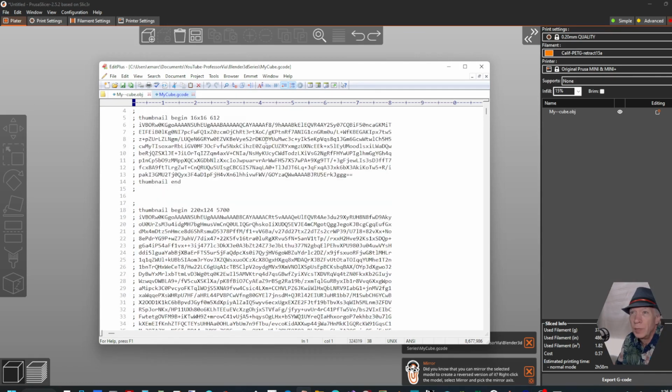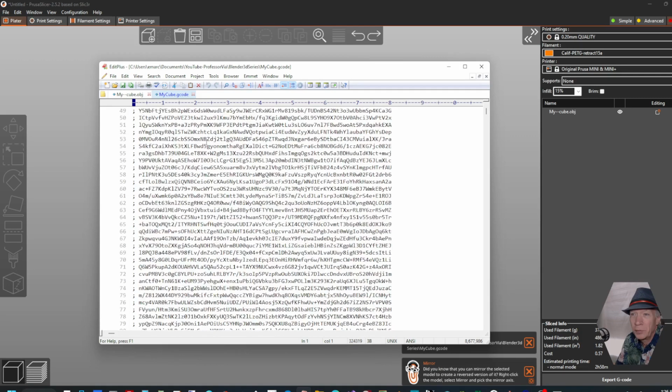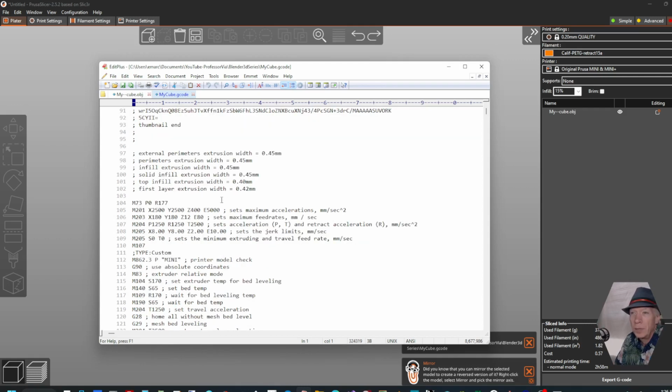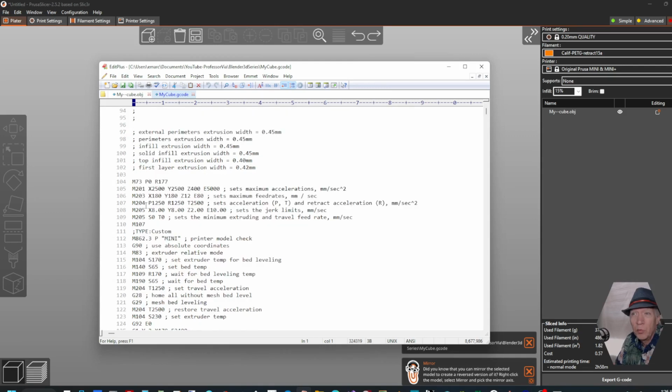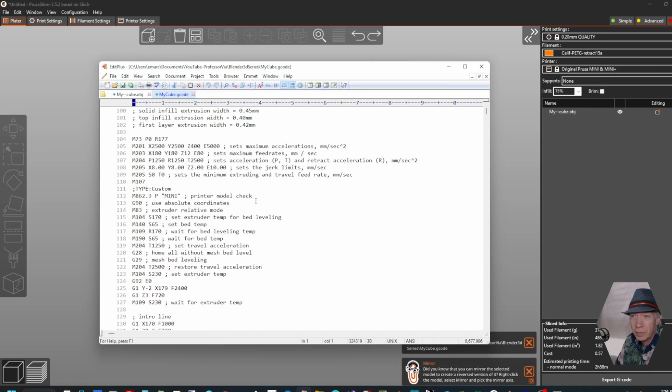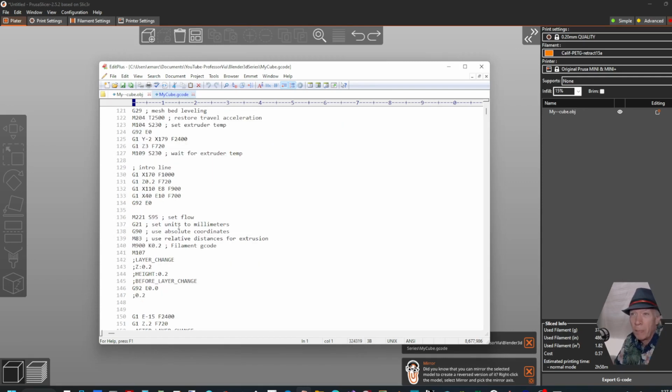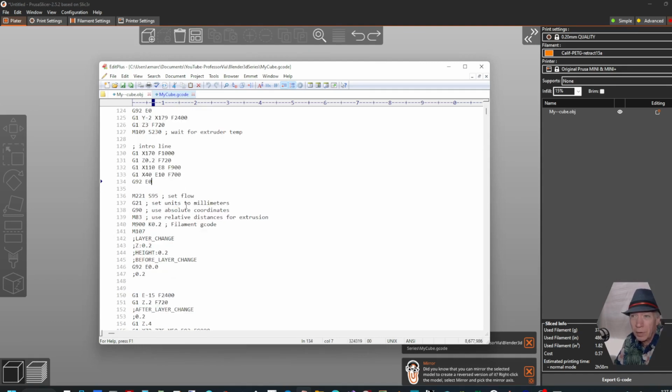Okay. These are like base 64 image files so that you can have thumbnails, but they're really comments in the G-code. They don't do anything for the G-code. They do things for the G-code viewers. Okay, and this is what all the movements come down to. There's a lot of M commands in here that are just basically setting acceleration and feed rates and stuff like that. How fast do I move between going to the points? But the actual, this is a little line that it prints just to get the filament started.